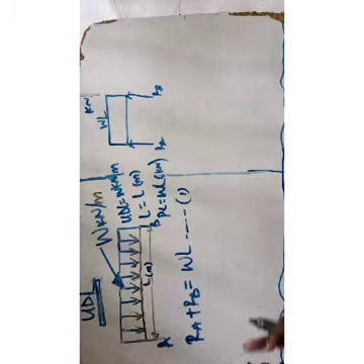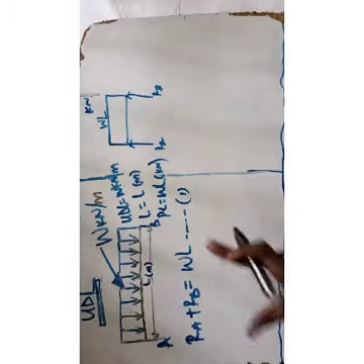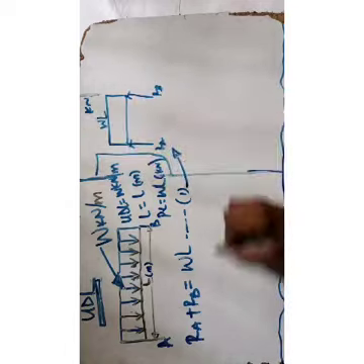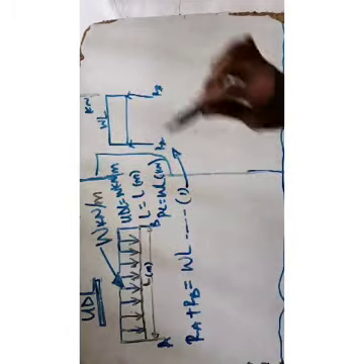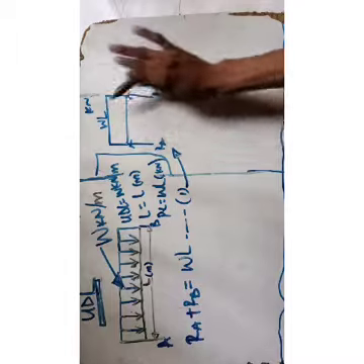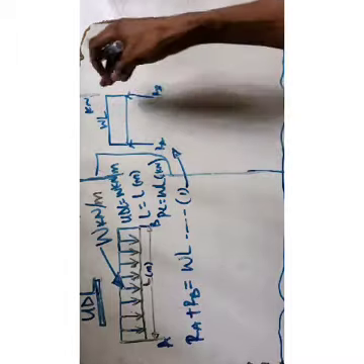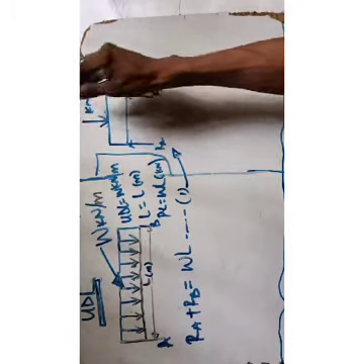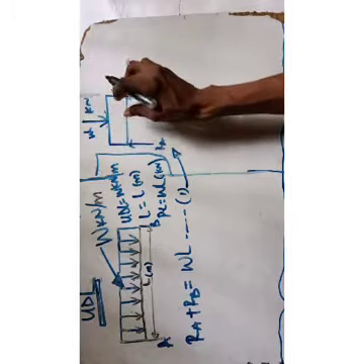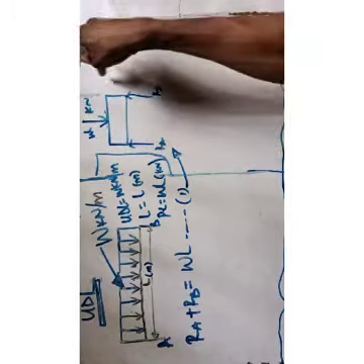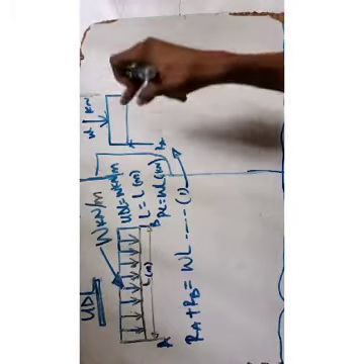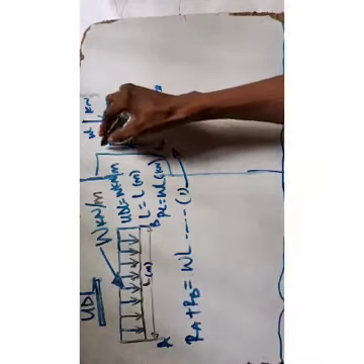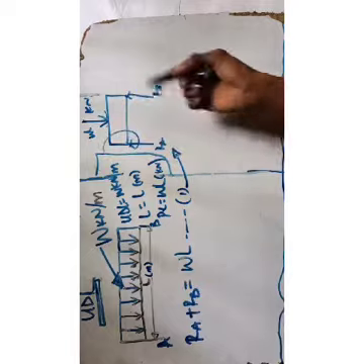Next thing you do is you now take moments. If you convert this, the diagram for this is like this. When I convert this to point load, just like the previous question of simply supported, you can now take your moment. But once you convert this to point load, it will always act at the center. Don't forget, it will always act at the center. So you have WL always acting at the what? Center. It will not act at the edge, it will act at the center. So let's say you want to take moment at point A here. This is also point A. What do you do?